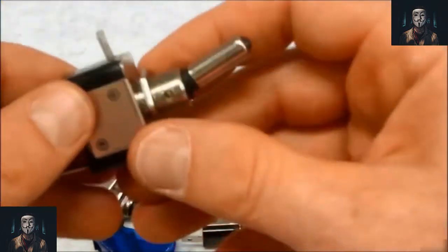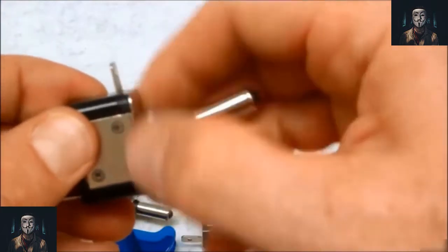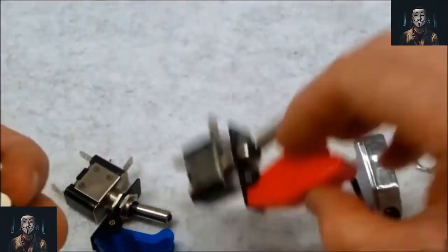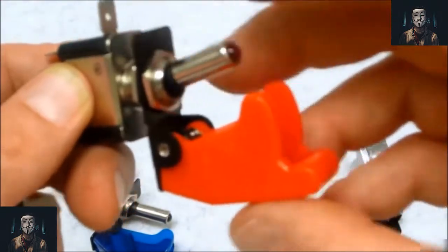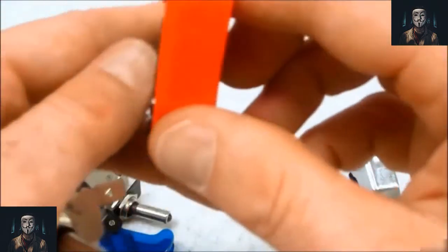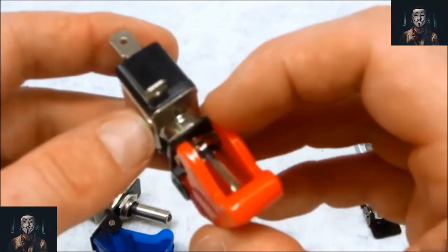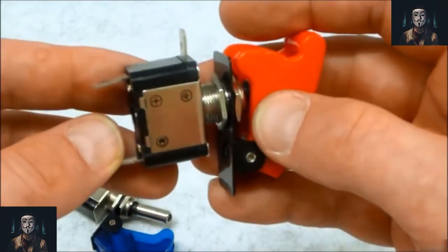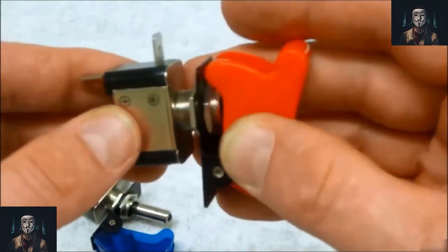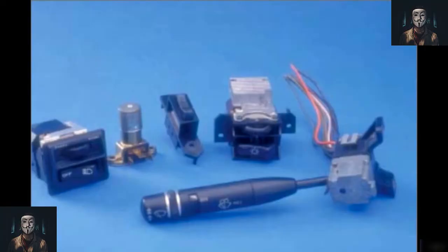Some electrical systems might require the use of a single-pole double-throw switch (SPDT). The dimmer switch used in the headlight system is usually an SPDT switch. This switch has one input circuit with two output circuits. Depending on the position of the contacts, voltage is applied to the high beam circuit or to the low beam circuit.